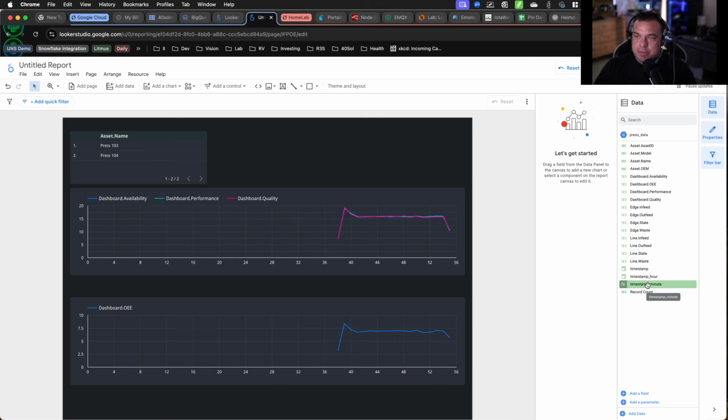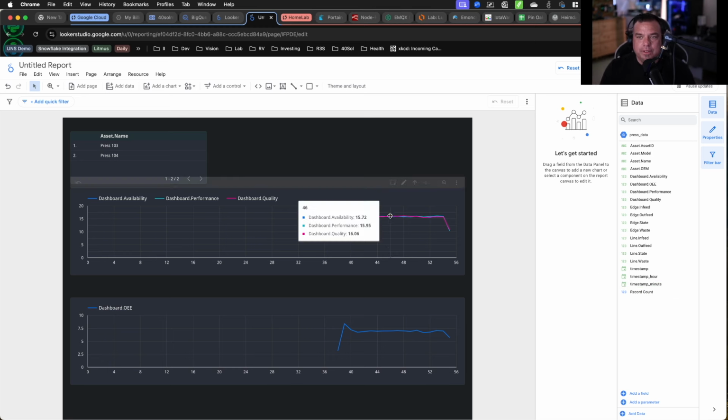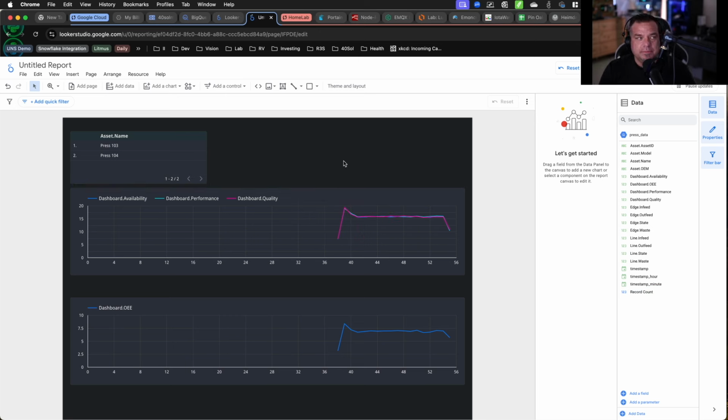I'm looking at time series data, but by default, Google just assumed I'd want to see it viewed across days, across weeks, across months, across years. That's the scope, that's the vision of cloud. But if I want to see it at a higher granularity, I have to take it to a place that, by default, it doesn't think you're going to want to go. Whereas a historian that you have on site assumes that you're going to want to look at data very granularly, not just to the second, but down to the millisecond, because it assumes that you're going to want to analyze process data, like the changes in instrumentation. That's just not something that cloud really thinks about all that often.